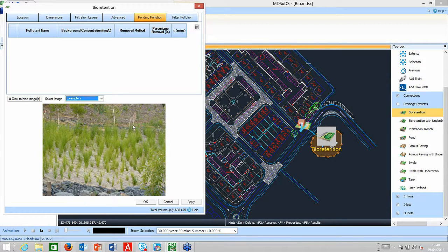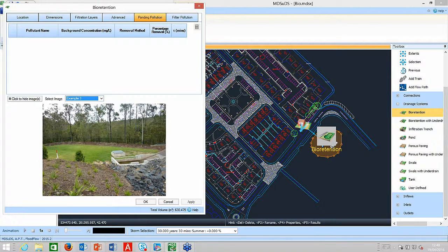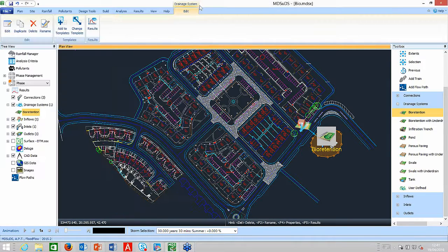Here's Joey here. You can see a little kangaroo. So some of the issues that they've had in Australia are washout and scour, when you have these steep sloping sites. They'll often put riprap in, larger stone, to prevent that erosion from happening. And again, there are all manner of means down to rain gardens, etc. There are many different types that we can look at.